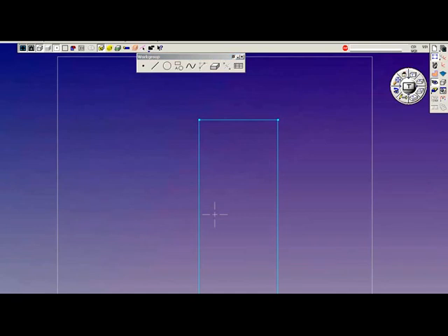The point selection is done, and we can now click on the chamfer tile, and we've got 4 options. We've got fillet, chamfer defined along the side, a chamfer defined along the depth, and a chamfer defined along the length. Let's use all 4 tiles on these 4 corners. So what we're going to do is generate a radius that's a 1/2 inch by selecting the circle here. We get a 1/2 inch radius right there.